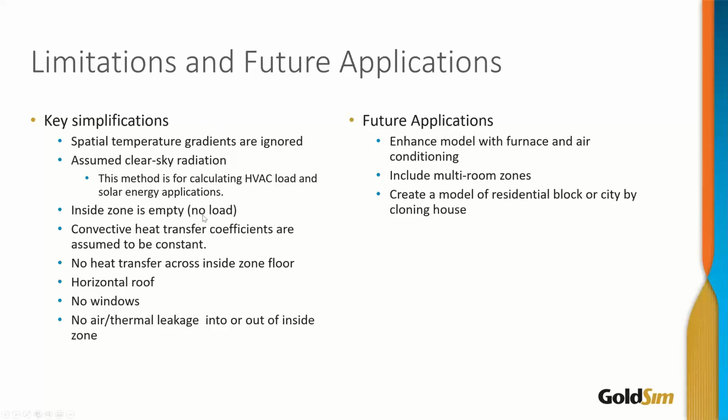We assume that the inside zone is empty with no loading, no lights, no people, no desk or furniture. I use constants for the heat transfer coefficients on the outside and inside surfaces. I do not consider the floor in the house. The roof is horizontal. You could make it pitched and include an internal zone to represent the attic. I do not include any windows or any air leakage into or out of the system.